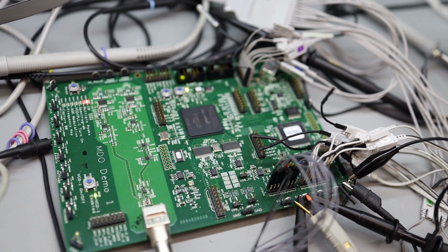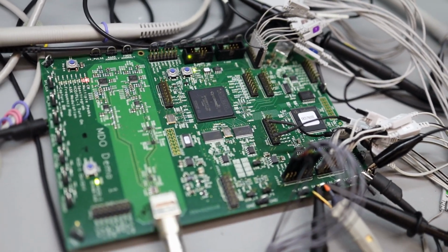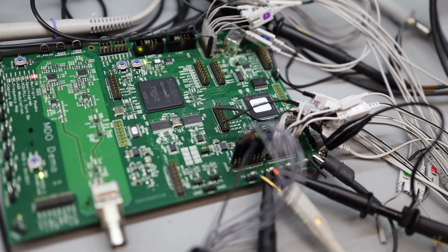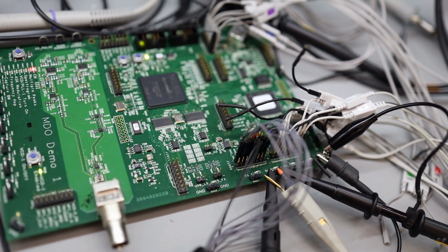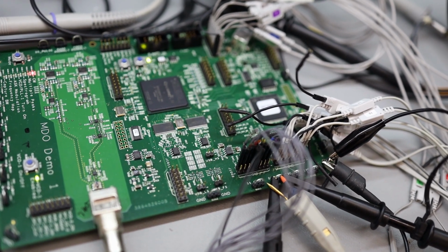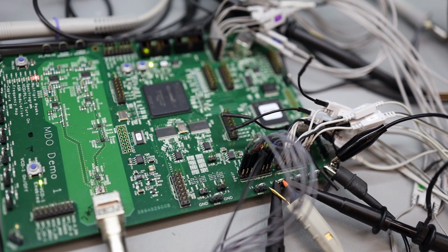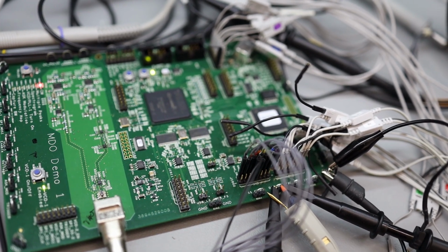On this hardware there is a DAC, and the parallel bus of the DAC is coming out on this bus right here. There's a header, and on this header every single bus line is available. It's of course a digital signal, and we will connect our oscilloscopes one by one, because we cannot connect all of them at the same time, to this digital DAC input and the analog DAC output.